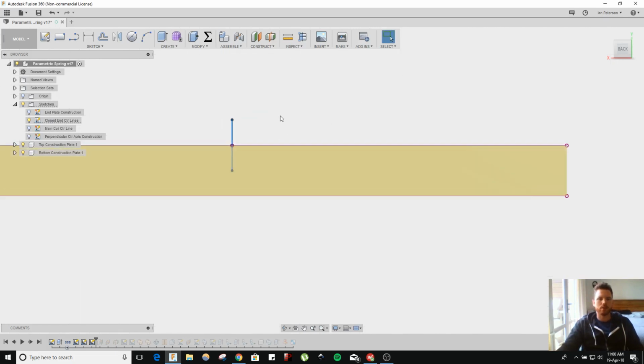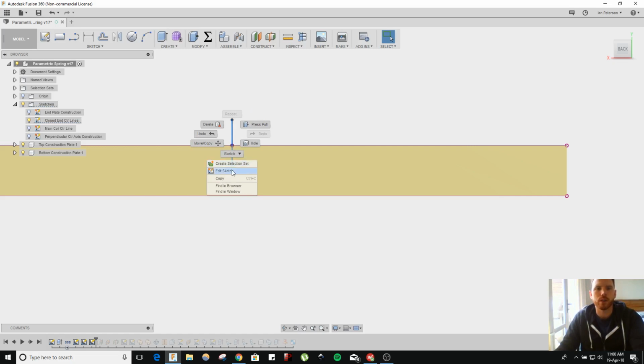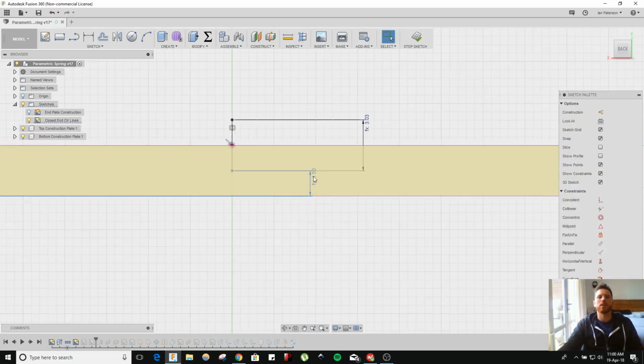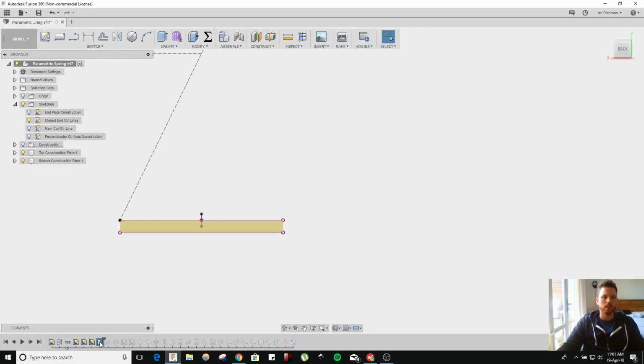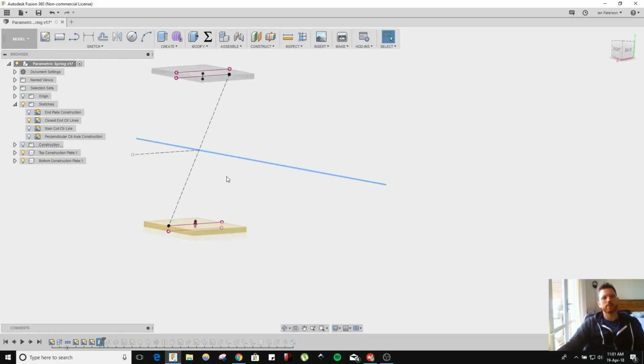Oh yeah, there was also another little thing in there. That just defines that there's half that starts halfway below the base of that plate. Yeah, so I'm going to stop that sketch now and move on. So this is an axis definition, and I'll use that later, but just know that it is halfway along the spring in the middle, perpendicular to its center axis.